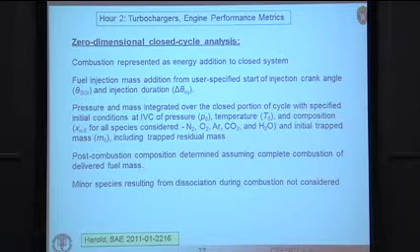Well, during that process, you might be able to account for the vaporization process of this injected fuel and assume that the latent heat of vaporization is somehow removed from the working fluid to give you a better estimate of the temperatures in the combustion chamber, again, assuming some sort of uniform temperature in the chamber.